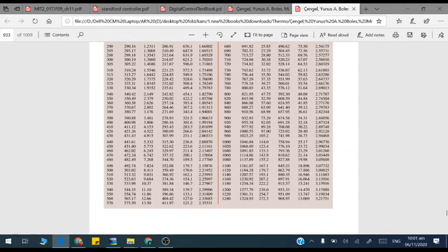So against this, look at 41 point something in the table. Here we have 760 with 39 point something and 780 with 43 point something. So in between, by doing interpolation between 760 and 780, you can determine the temperature.